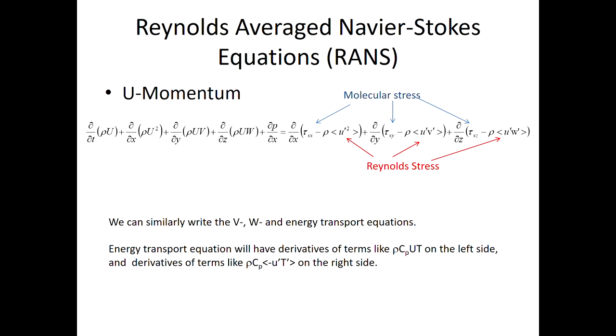So for example, when you fan a fluid creating eddies, you may be using it to carry a hot part of the fluid to the cold part of the region and vice versa. So this is what happens in turbulent flow. Eddies do the job of transporting momentum and also energy in addition to the molecular processes. The molecular processes are very small, very weak, very slow. So very often turbulent flow helps transport mass, momentum, and energy very efficiently.